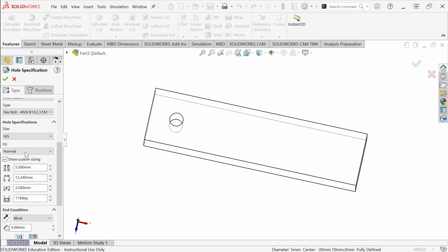So an M5 has a diameter of the hole of 5.05. And I'm going to change that to just a 5.0, maybe everything else the same. So now we are non-standard with our hole, but the hole is a little smaller. So this would not fit the standard M5 bolt. It'd be a little small. But we're going to make the hole the same size as our hole.